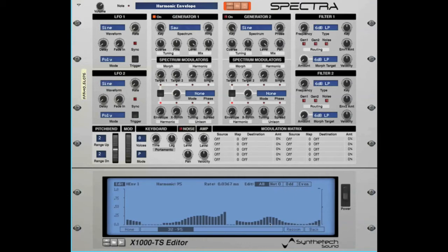To copy a single value across a range of multiple stage elements, select the stage element which contains the value you want to copy. Next, click on the rate level value in the caption. Notice how it remains highlighted. This is indicating you are copying the current value. Next, click the selected element again, and while holding down the mouse button, drag the mouse across the range of elements you want to set to this value.